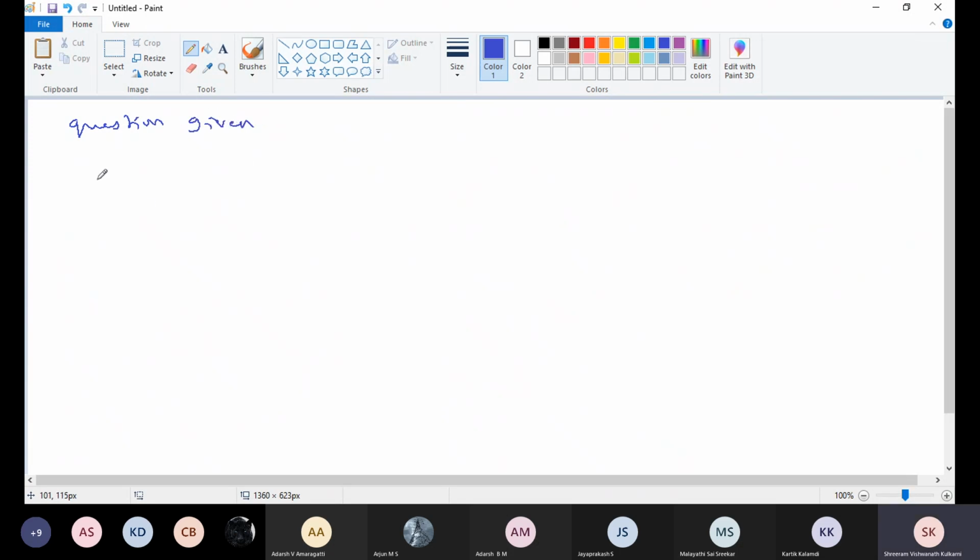first we need to mark all the variables. Then for Y parameters KCL, for Z parameters KVL. Now for Z, we know V1, V2 in terms of Z11 I1 plus Z12 I2, Z21 I1 plus Z22 I2.